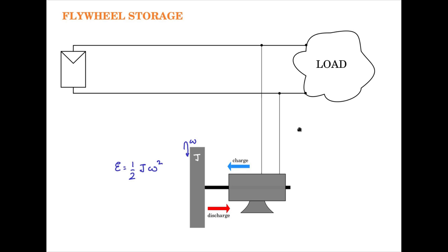And here again you will see that there is the efficiency of the motor that comes into the picture. So this will have an efficiency of around 80%. So this system will have an overall efficiency in that order, because it is just one component that will come into the picture here, which is the motor, and directly to the shaft of the motor the flywheel is fixed. So you can expect practical efficiencies of around 80% in this system.